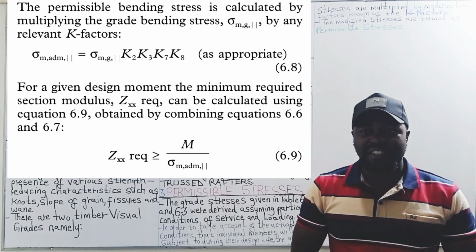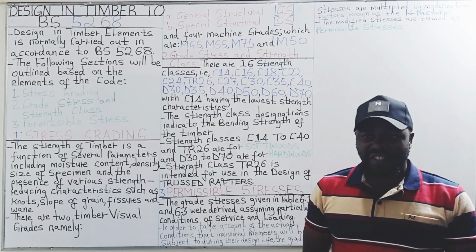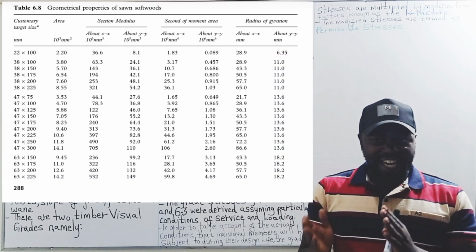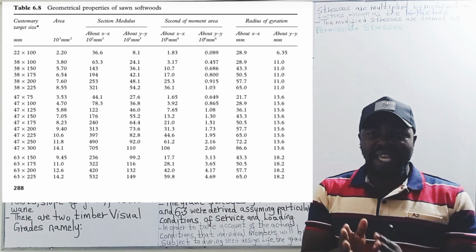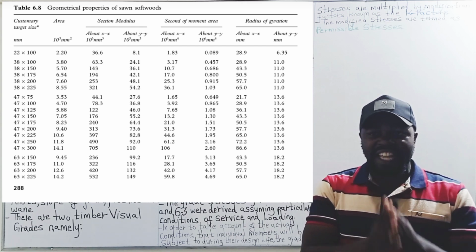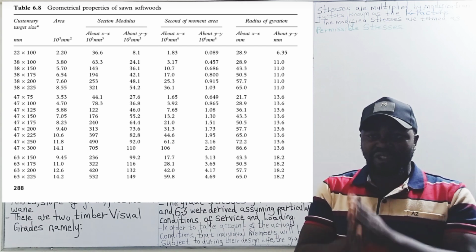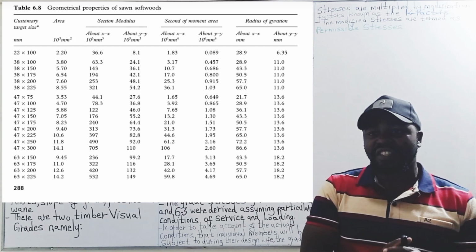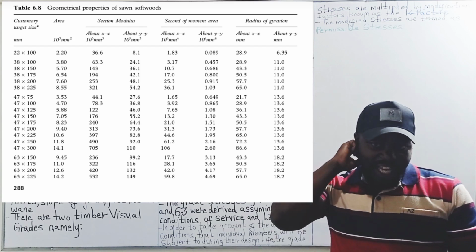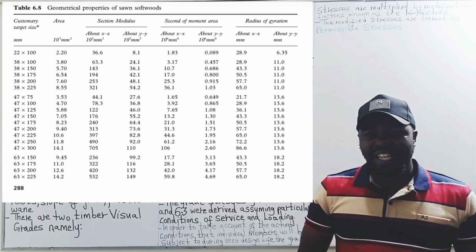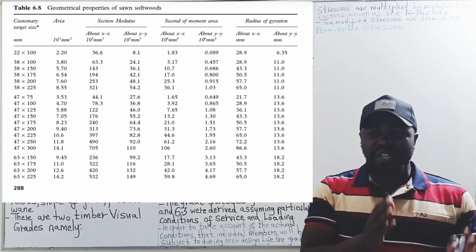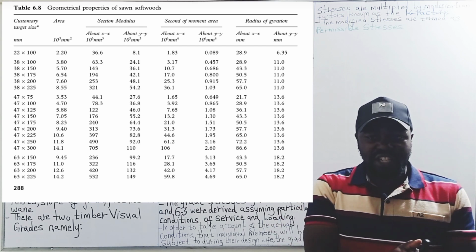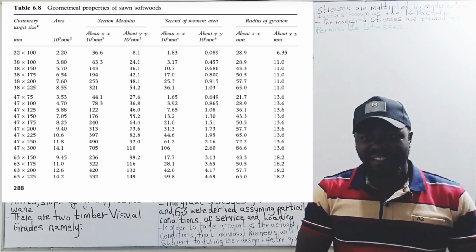parallel to the grain. A suitable timber section can then be selected from tables NA2, NA3, and NA4 of BS EN 336, that is structural timber sizes permitted deviations. These tables give the commonly available sizes of respectively sawn timber, timber machined on the width, and timber machined on all the four sides.